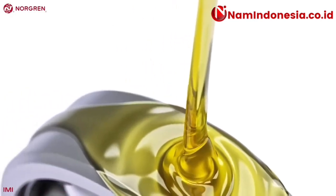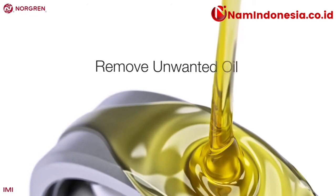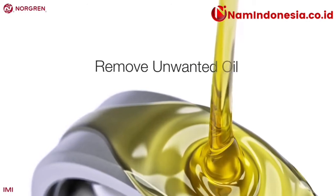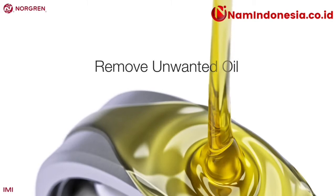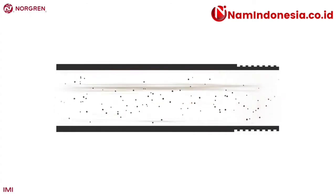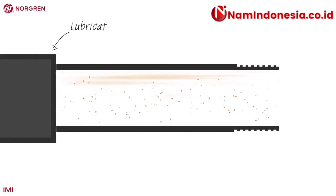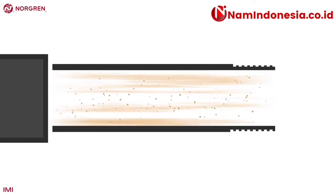As well as removing water, we need to remove unwanted oil, usually from the compressor. This contamination can cause issues itself, but when mixed with moisture, it creates a substance that isn't good for lubrication and can stick to moving parts inside pneumatic components, slowing cylinders, for example. But why do we add oil if we have already gone to the effort of removing it? Later, we'll talk about adding oil to a system with a lubricator. This clean, controlled oil ensures smooth running of components and is very different to the dirty, unpredictable oil from a compressor that may be circulating through a system.